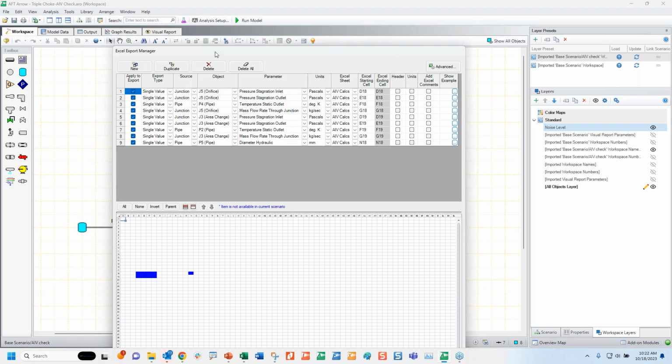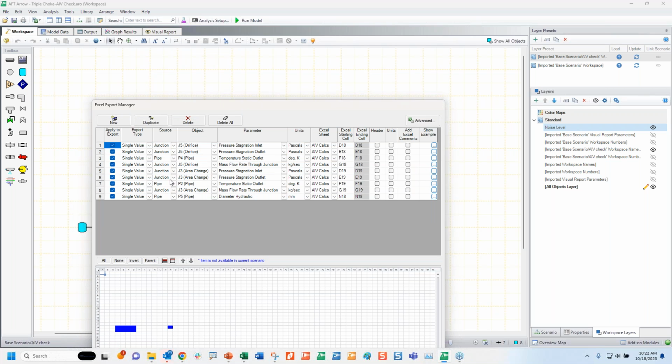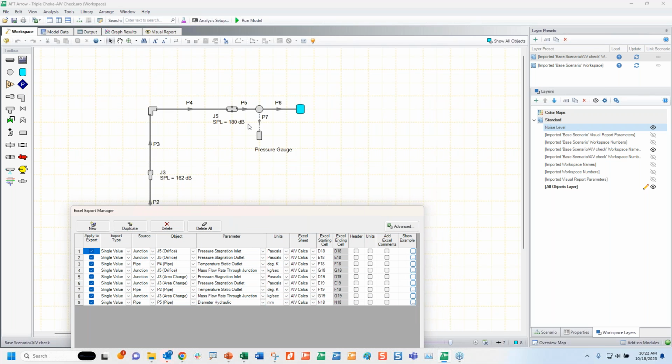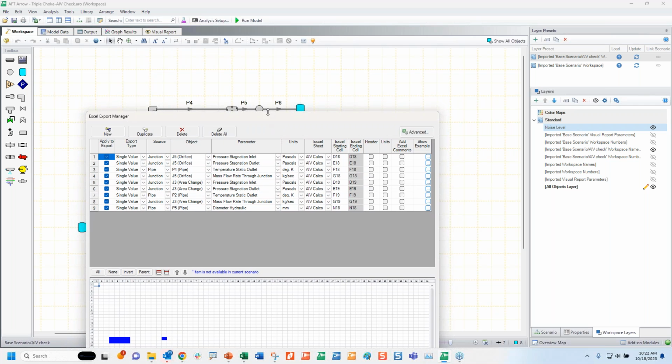From the 4th to the 8th, it's the same, but for the second source of vibration, which would be J3, where sonic choking is also occurring. If sonic choking were not occurring here, you wouldn't mention it as a source of vibration. And finally, pipe 5, which is the pipe connected to the discontinuity, to evaluate the discontinuity in the system.